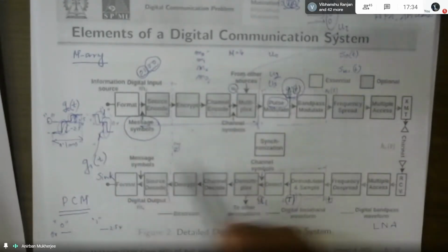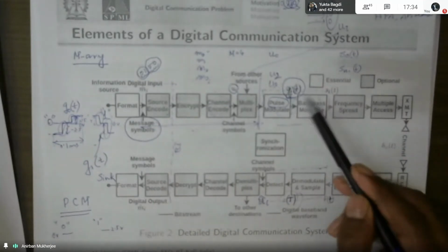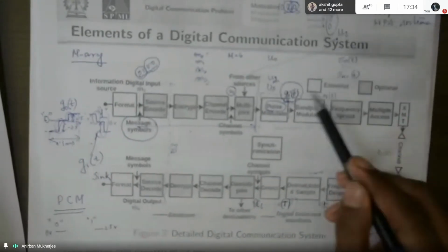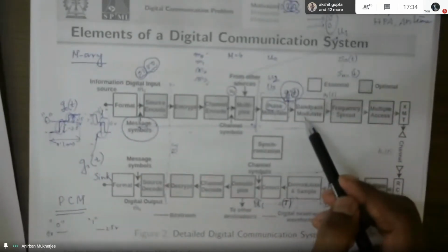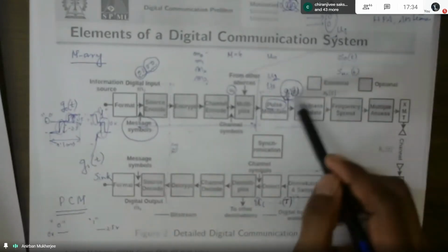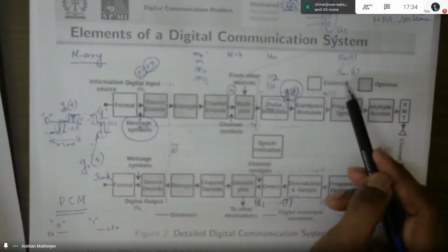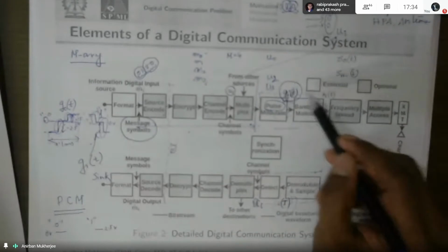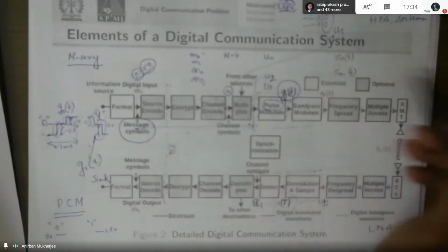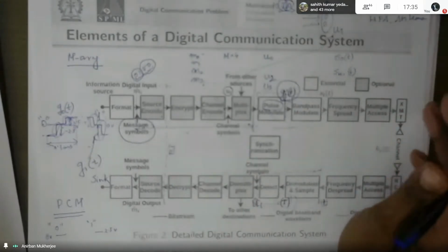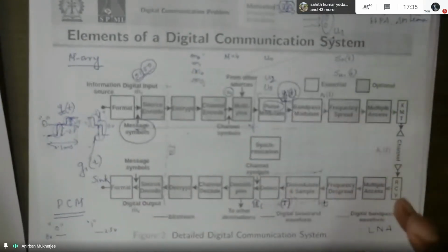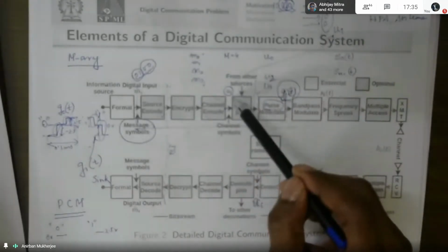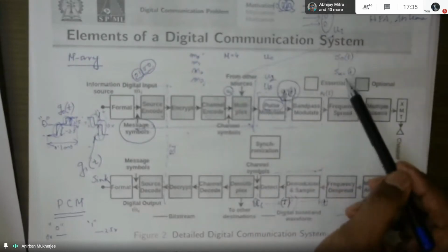Maybe PCM waveforms. Now you are doing a wireless transmission, so this pulse will not go to the channel. I have to do a bandpass modulation. That means bandpass modulation from g0(t) to g3(t), I will generate s0(t) to s3(t). Sometimes we put pulse modulation and bandpass modulation in one block, and directly from the bit stream we generate this. Philosophically we break things so that all the steps are clear. Directly, sometimes, from the channel symbols u0 to u3, you just generate s0 to s3.